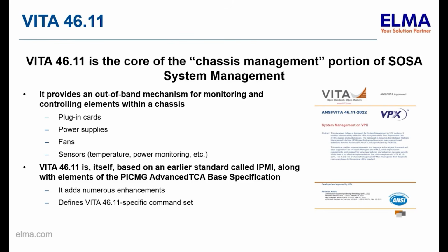VITA 46.11 is the core of the chassis management portion of SOSA system management. It provides an out-of-band mechanism for monitoring and controlling elements within the chassis, including plug-in cards, power supplies, fans, and sensors. VITA 46.11 is itself based on an earlier standard called IPMI, along with elements of the PICMG Advanced TCA-based specification. But it adds numerous enhancements and defines a VITA 46.11 specific command set.